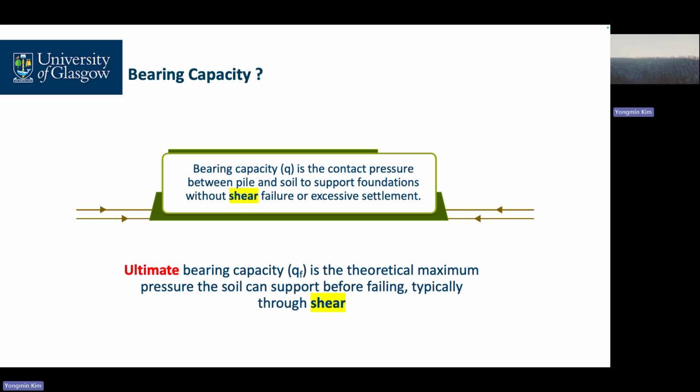How many times have I said bearing capacity? Can't count. So what is the bearing capacity? Contact pressure between pile and soils. Soil pressure to support our foundation system without shear failure. What is the ultimate? Same, the maximum pressure right before soil fails in shear.